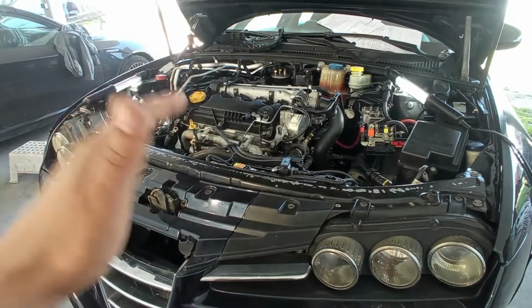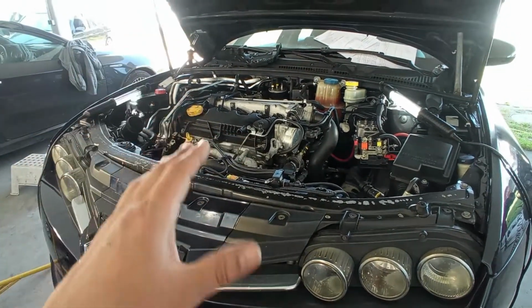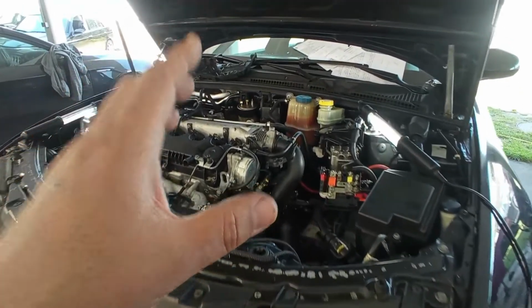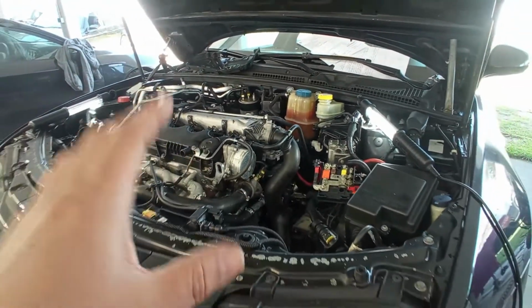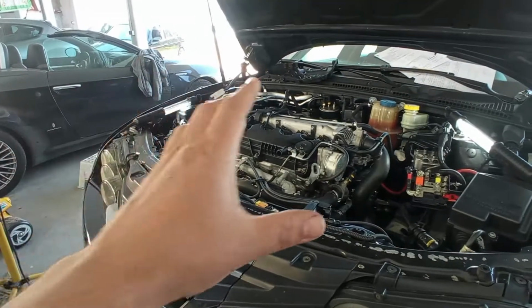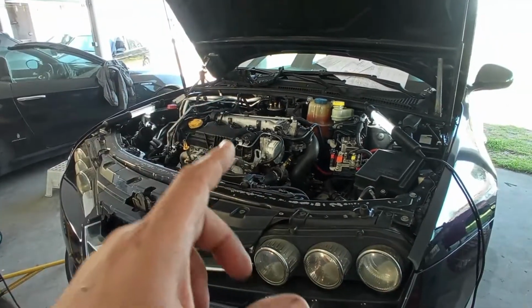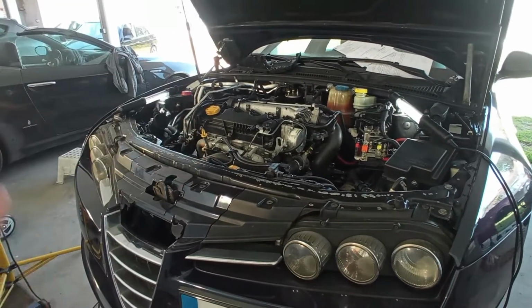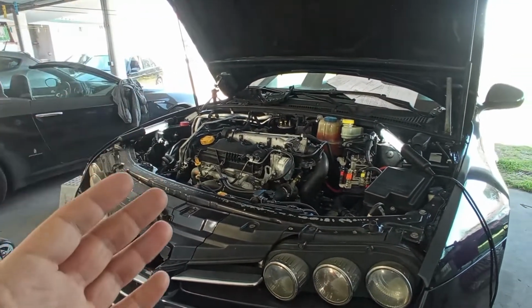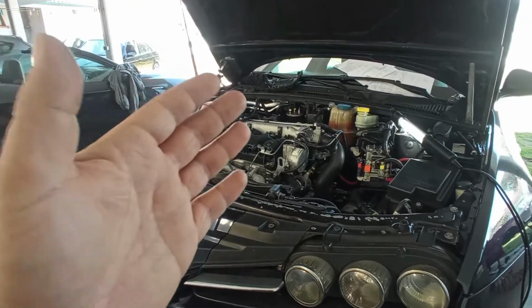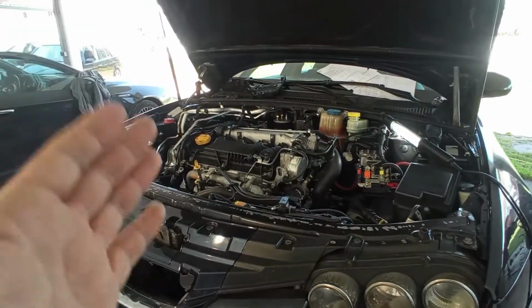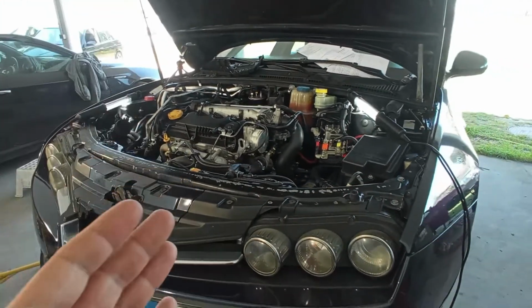Yes, I know many of you say just delete it, but wait, what caused the problem of the DPF? Because if it is happening, it is because something is wrong, something is clogging the DPF, regenerating at every 31 kilometers. That's nothing. It has to do 300 or 400 kilometers at a time. So even if I remove the DPF, I still have what caused the problem of that, okay?